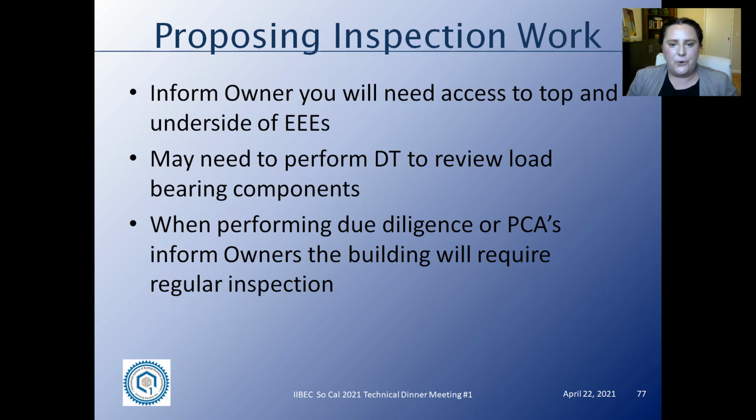You may need to perform DT to review the load-bearing components. So if you have an enclosed soffit, the only way that you're going to see the load-bearing components is if you actually get in there. So that it's going to require opening up some of these areas. And just keep in mind too, this has to happen on a 6 or 9 year cycle. So you're going to need to do these DTs every 6 or 9 years, depending on the construction you have.